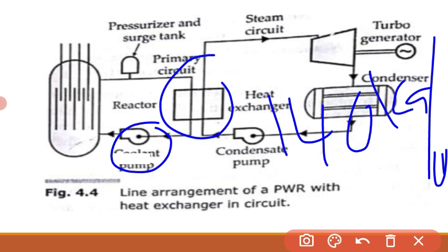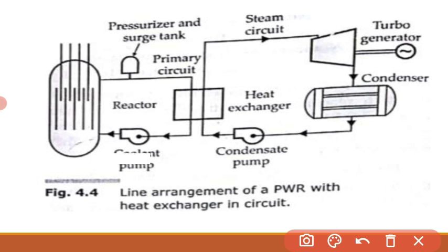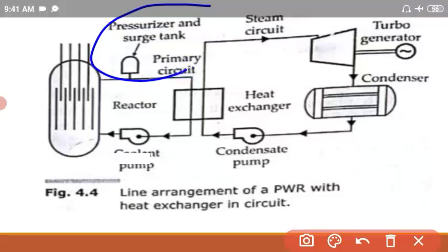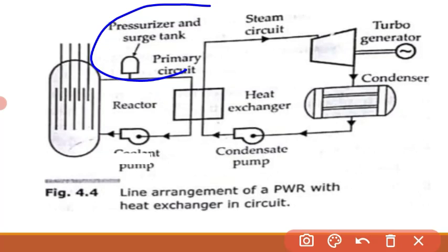The secondary loop comes here. The boiler has a heat exchanger and a steam drum. Related to this tank, I will discuss the pressurizer and surge tank tapped into the pipe loop, which maintain constant pressure in the water system throughout the load range. An electric heating coil in the pressurizer boils the water to form steam which is collected in the dome.